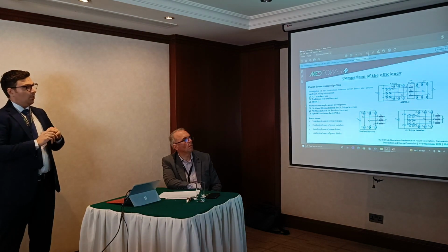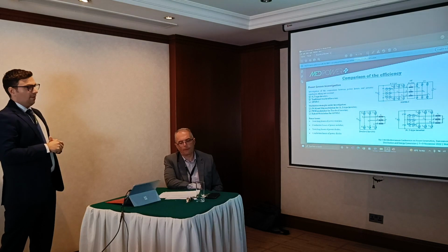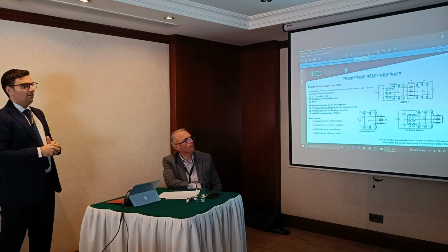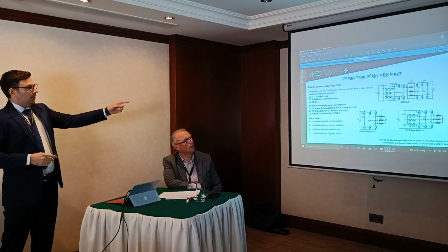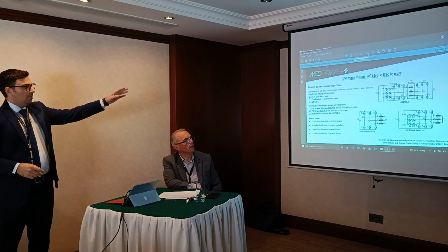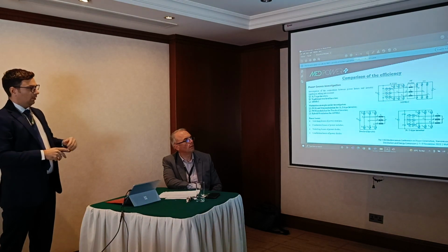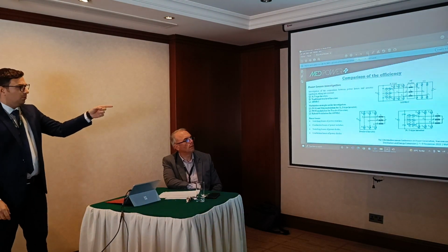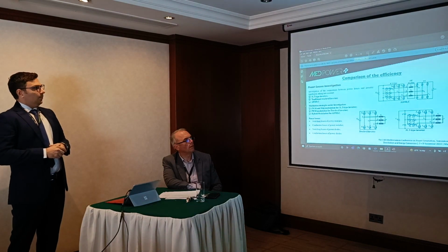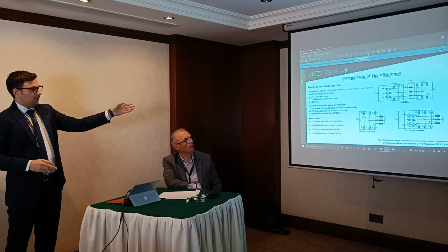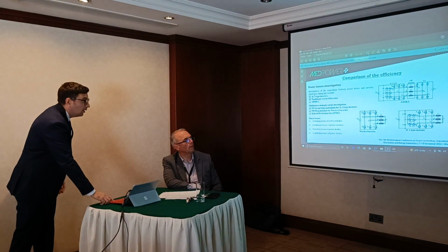In this paper, a comparison of the efficiency between the asymmetric hybrid multilevel converter, the 2-level converter, and the 3-level T-type converter has been performed. In particular, we regard the modulation: PWM and step modulation for a 3-level T-type in wye-connected load, PWM modulation for 2-level, and hybrid modulation for asymmetrical. We consider also switching losses and conduction losses for both power switches and power diodes.